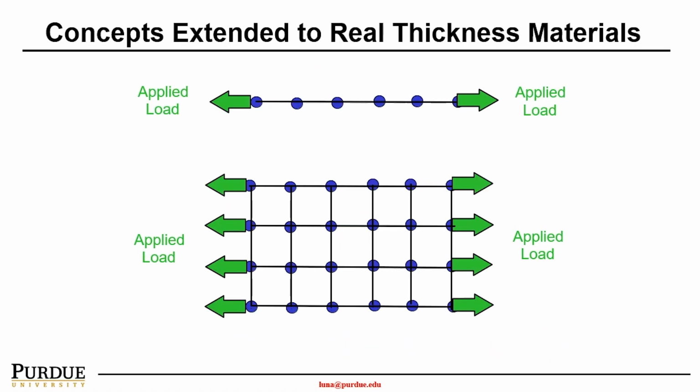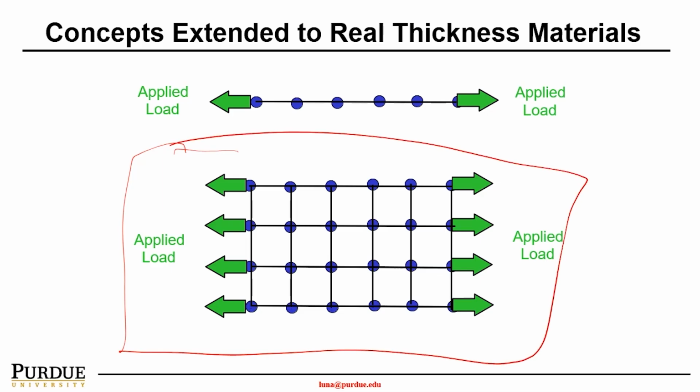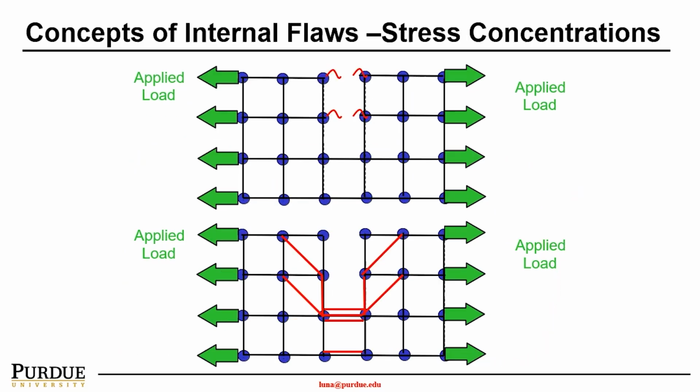So therefore, the material will break eventually. If we look at it from the atomic structure level, we can see many layers of atoms, and then we apply loading uniaxially. This load will be transferred uniaxially through the material. However, if a certain bond is broken, the applied load can't pass through it and will concentrate in this area.